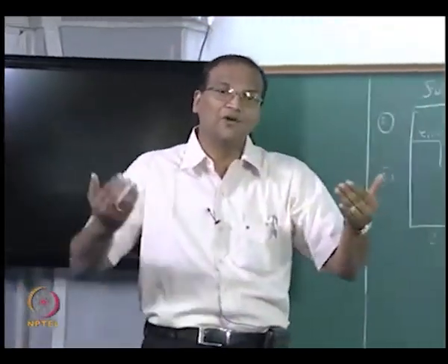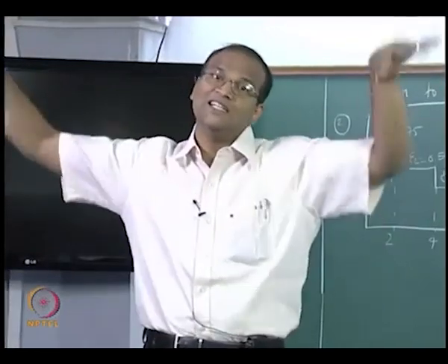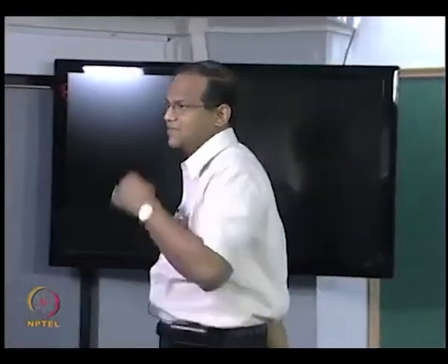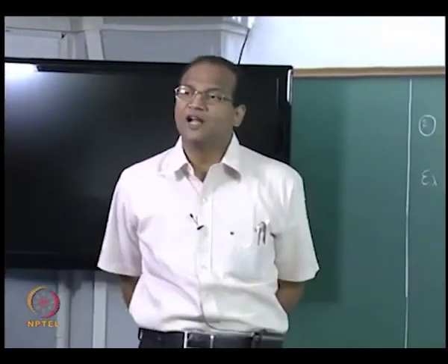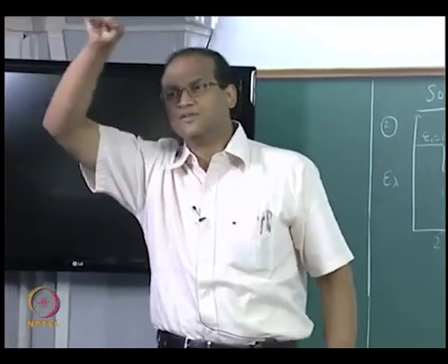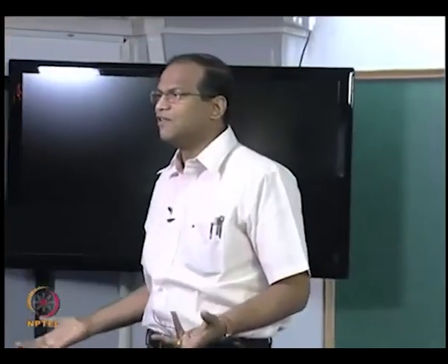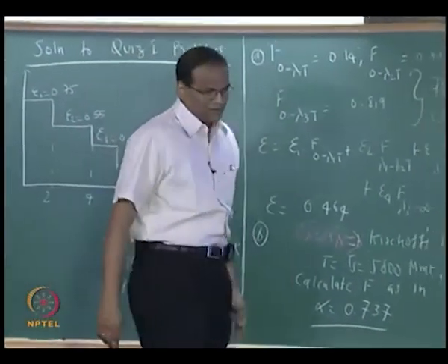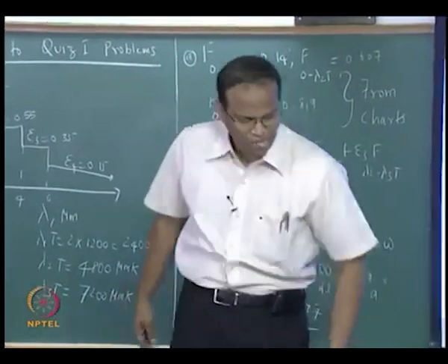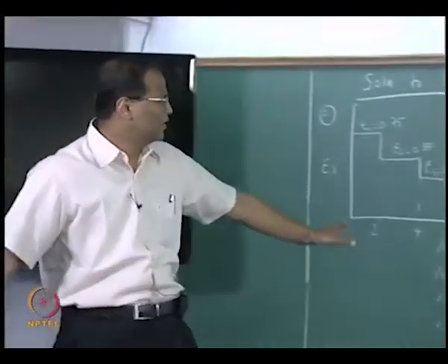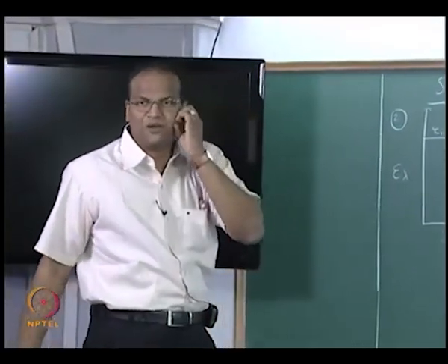Alpha is basically the absorptivity of the incident radiation. So the incident radiation is coming from somewhere, from the sun. So you have to take the temperature of the sun. Otherwise I should give you information on I lambda. I will say no, it increases from 0 to 4000 watts per meter square, decreases, increases. Since I have not given the distribution, you have to use the black body function, and repeat the same procedure, except that you will use 5800 Kelvin. Now we got the alpha. So 6 marks plus 6 marks, 12 marks.